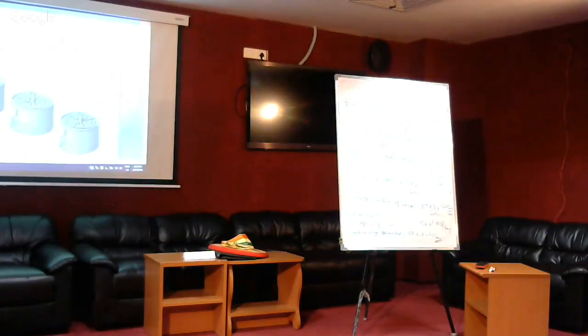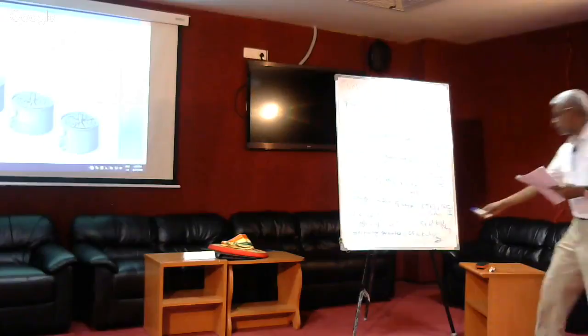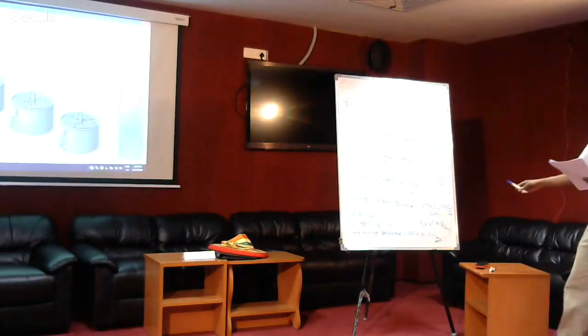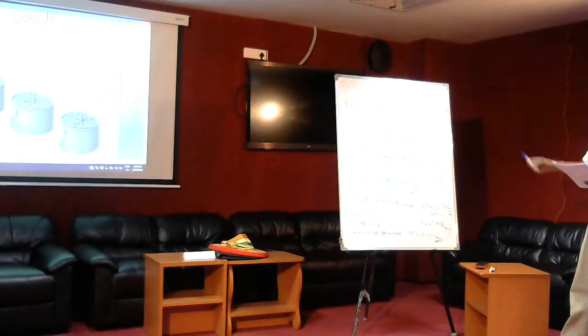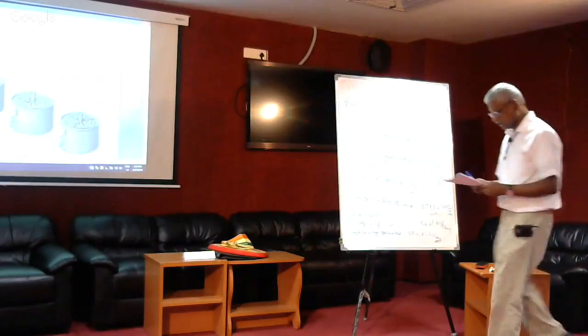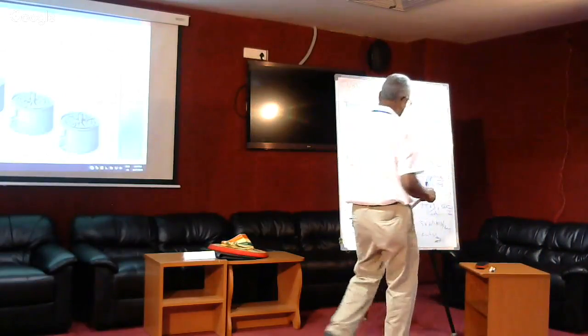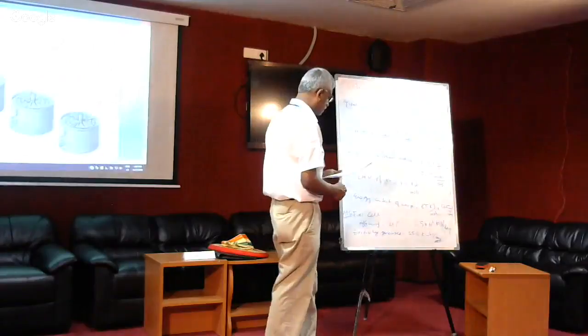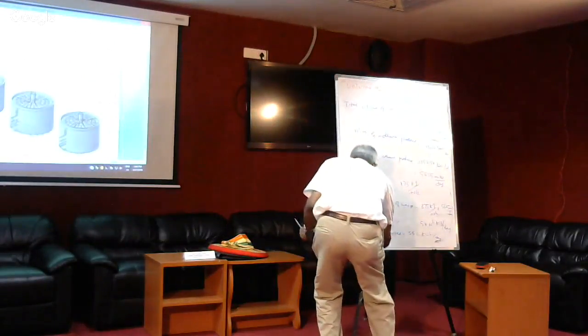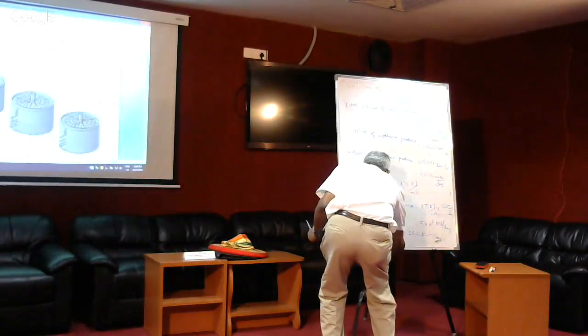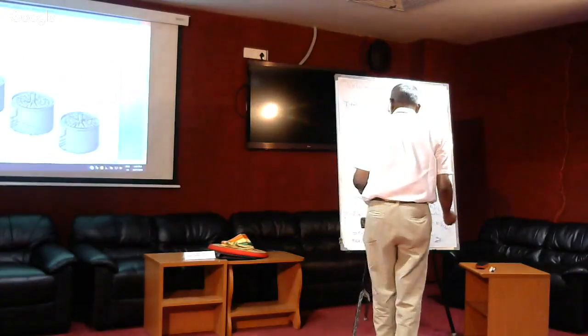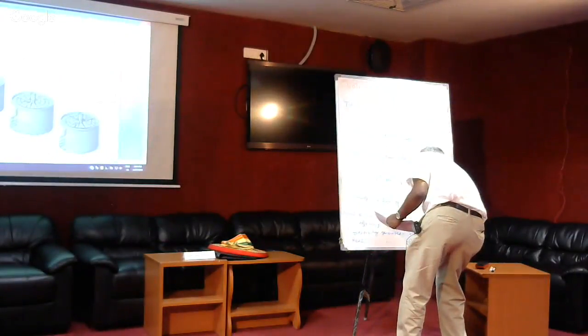So if I take 1 watt times 60 seconds per minute times 60 minutes per hour, I can then get kilowatt hour in terms of joules. When I do that conversion, I get that electricity generated is 556 kilowatt hour per day, and heat generated is 834 kilowatt hour.